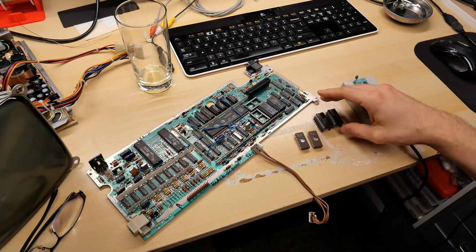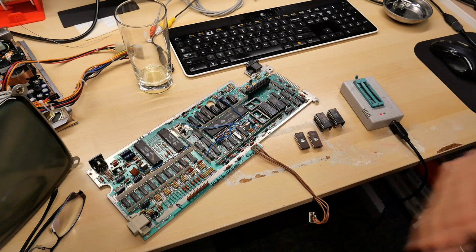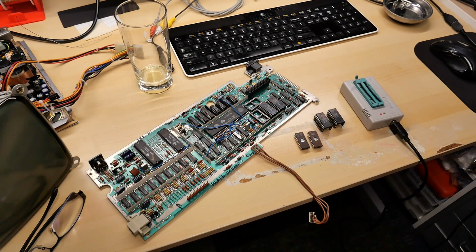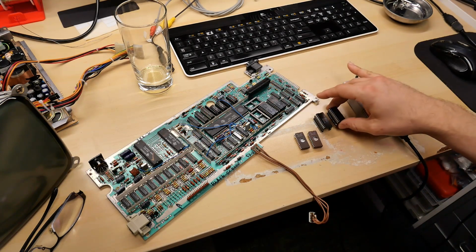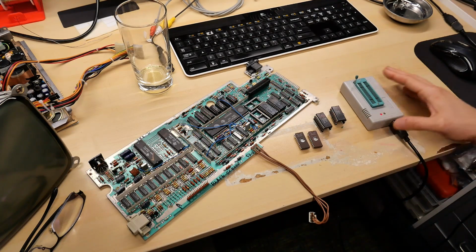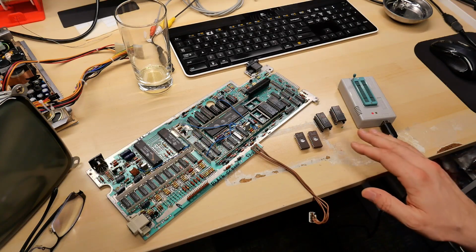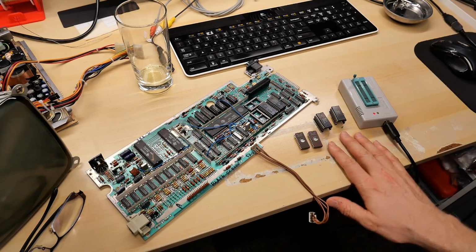So that tells us that both of these EEPROMs are actually totally fine. And when I read them on that other Unipro programmer on that DOS computer, and it was coming back with all Fs, that was a problem with that software. So I haven't used that very much. I've used this thing a ton. So clearly I'm not quite up to speed on reading EEPROMs with that.